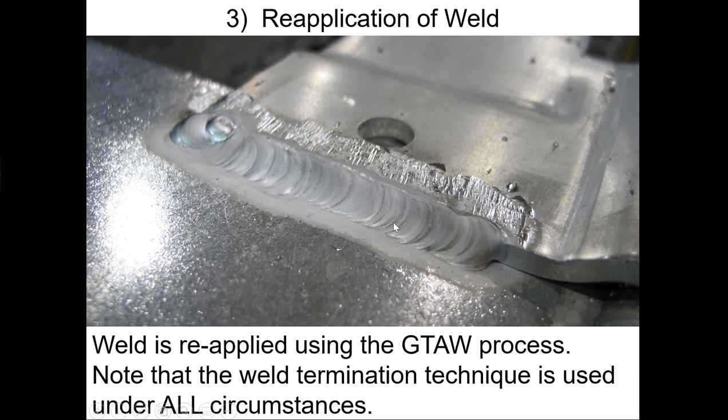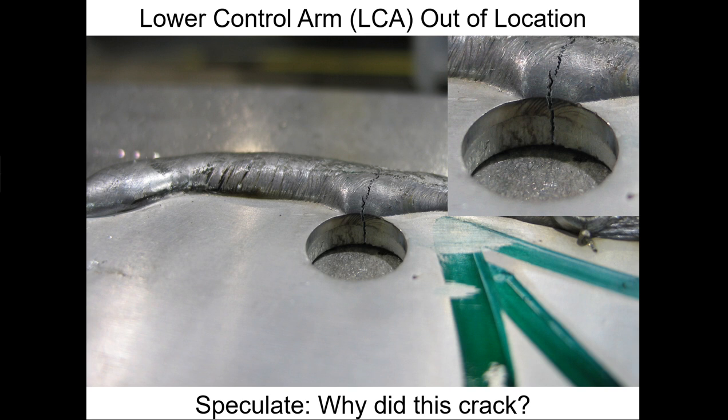There's no call out that says you have to build up any welds beyond the toe. Remember, this bump is referred to as reinforcement. As long as you're flat or more, especially with the TIG process, you got everything you need.